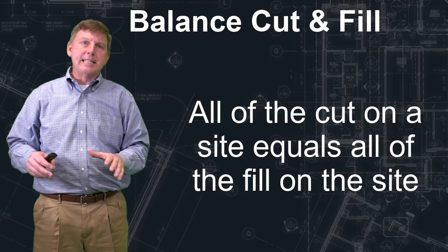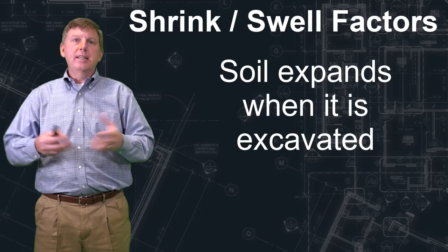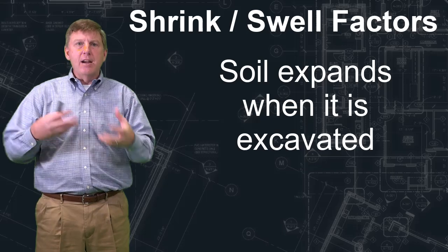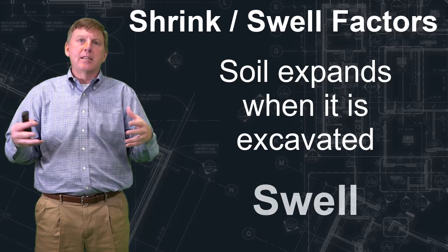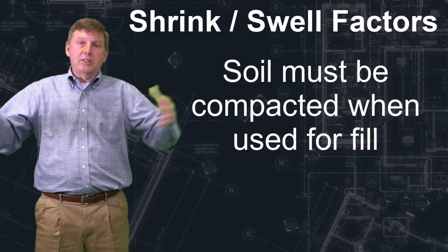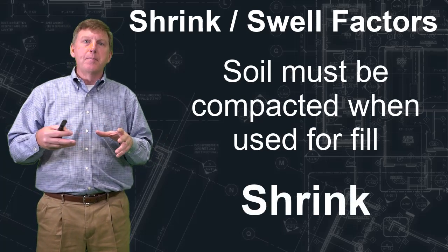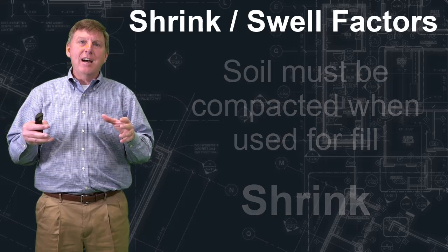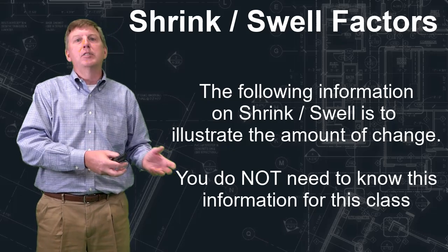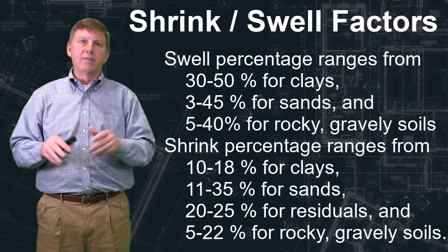If it were only that easy, you see, when you pull earth from a site, it expands, right? Because you're breaking it up. It's no longer compacted in the earth. Air infiltrates it and stuff, so it kind of expands. That's called swell. And when you put earth into a site, you've got to compact it down. So you take all this earth and you put it in, you have to compact it down. And that's called shrink. So you have to calculate how much you can compact earth to a spot, how much it'll swell from a spot, to figure out exactly how well you balance the cut and fill.